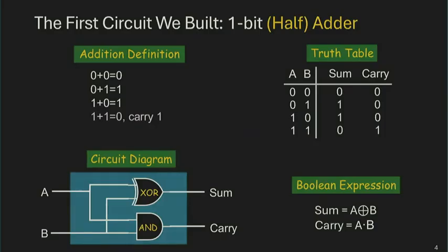All right. So the first topic is about designing a binary adder. The first circuit that we saw in this lecture is actually an adder circuit. This is before we even discussed the axioms and theorems of Boolean algebra. I showed you just one example where you can convert some behavior specification of 1-bit binary addition into a truth table. You can derive the expression from that truth table by just mapping the two output functions into corresponding gates.